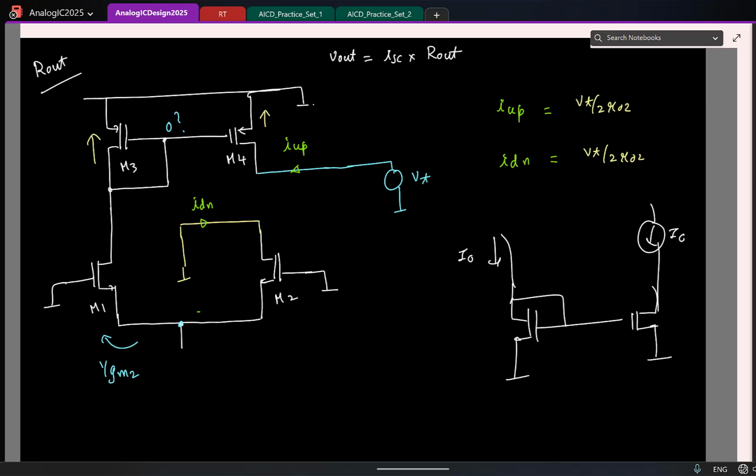Remember, as I mentioned, for the gate voltage to be set properly, there needs to be a feedback. Here you are just pushing in a current. Why will this gate source care? It is floating somewhere. Unless you have some mechanism to sense the current that you are pushing and the current in the transistor, sense the difference and correct the gate or source, the VGS is not fixed. Is that clear?